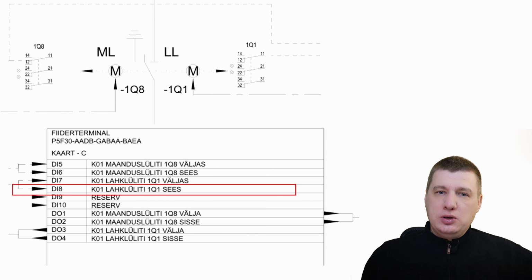Think of the disconnector like a bridge on a train track. When the status says on, the bridge is down, the track is now continuous, and the train, once the main signal, the circuit breaker, is turned to green. If the bridge isn't confirmed as on, the signal stays red to prevent the train from falling into the gap.